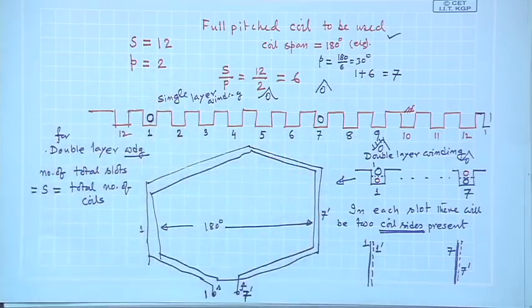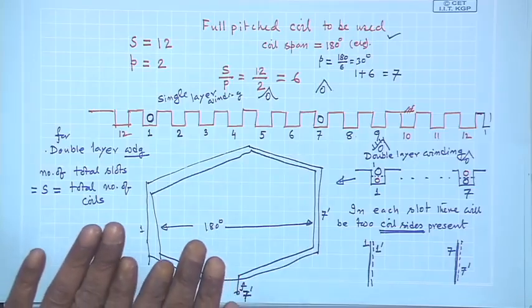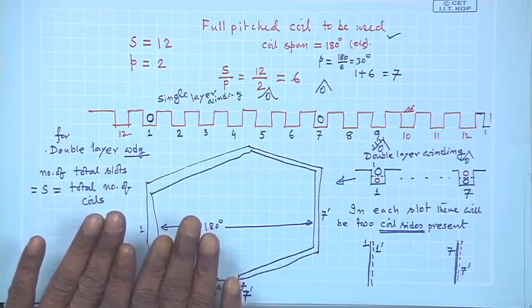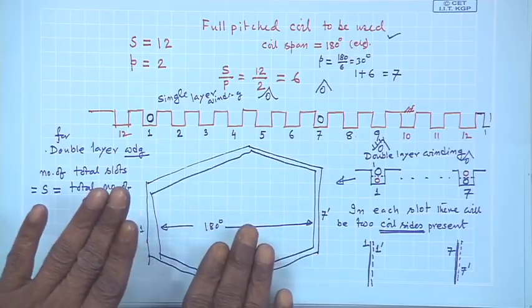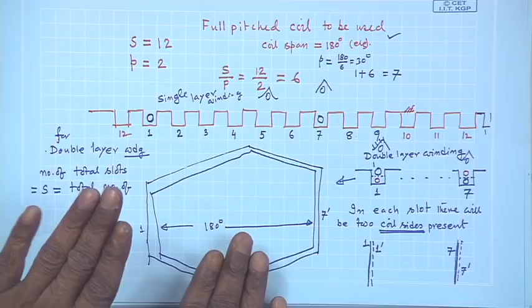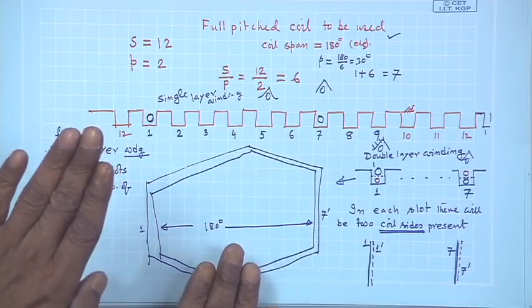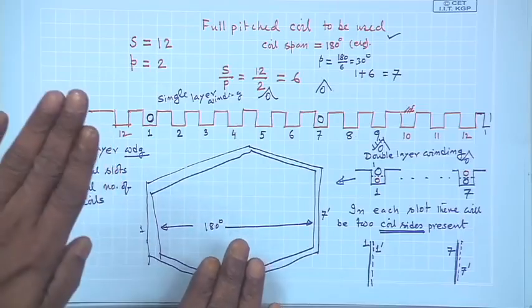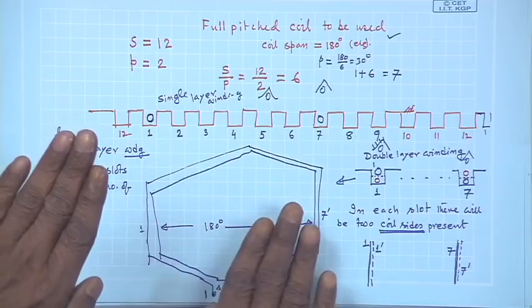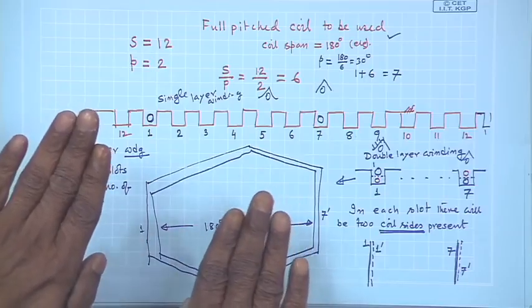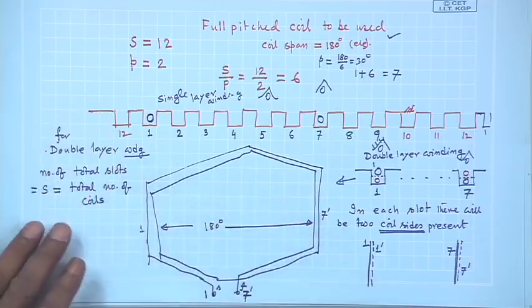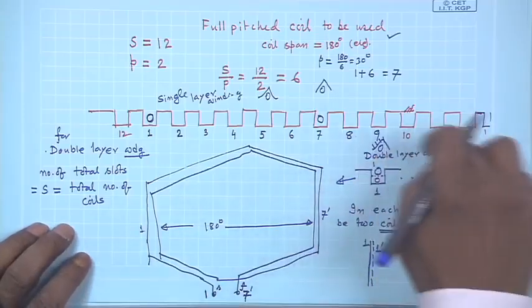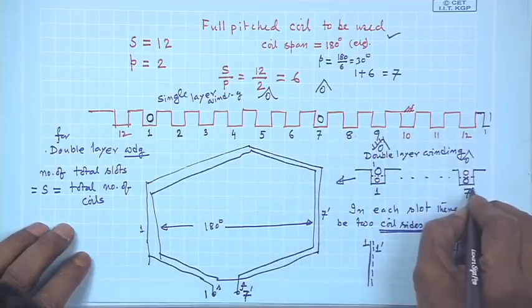So, if you look at any coil of a rotating machine using double layer winding, the coil shapes are not exactly in the same plane. One coil side is slightly above, indicating that whichever slot it occupies, it will occupy the upper deck, and the other will be in the lower deck. So, one goes and returns to 7 dashed.